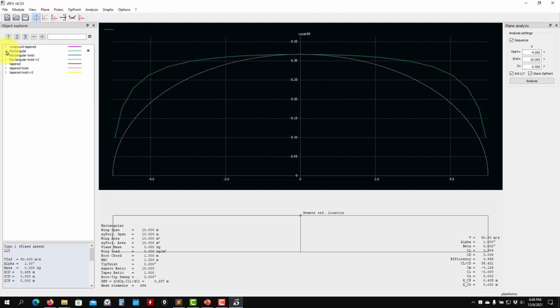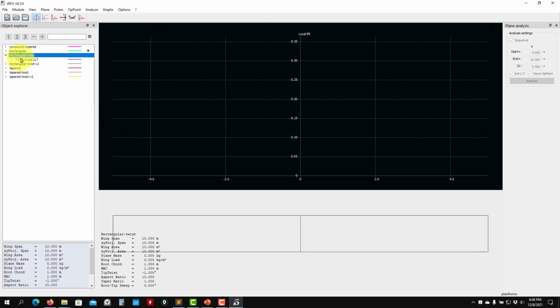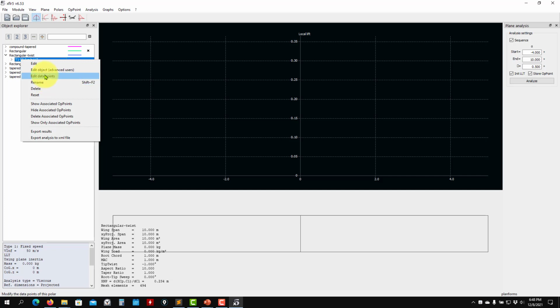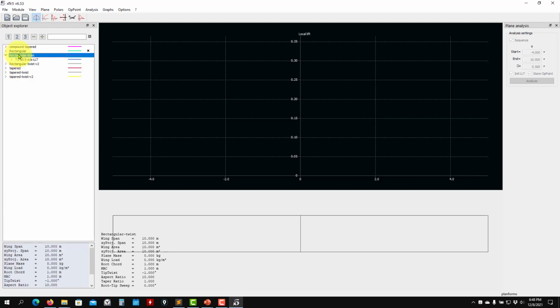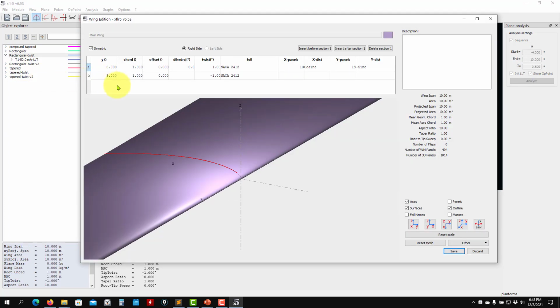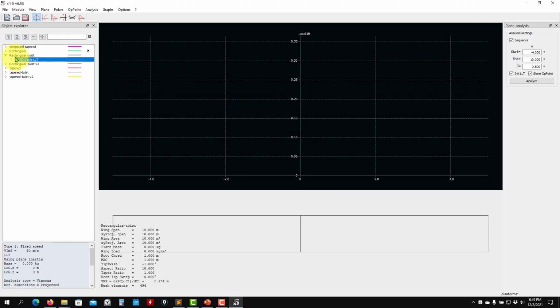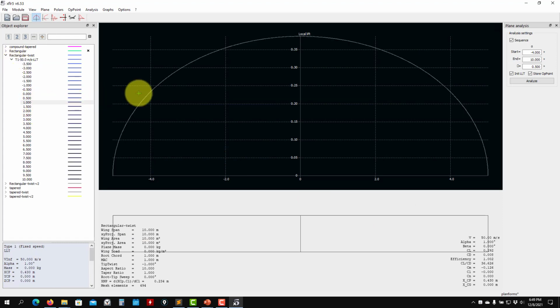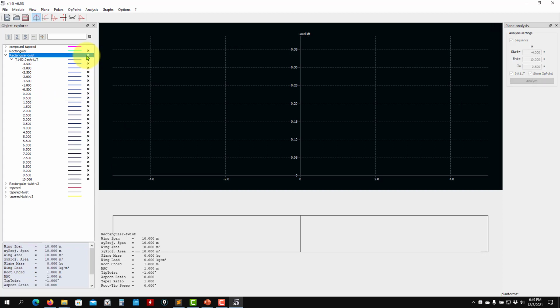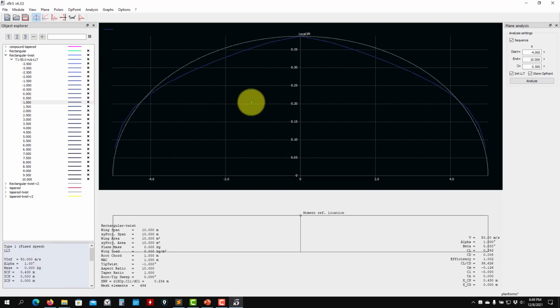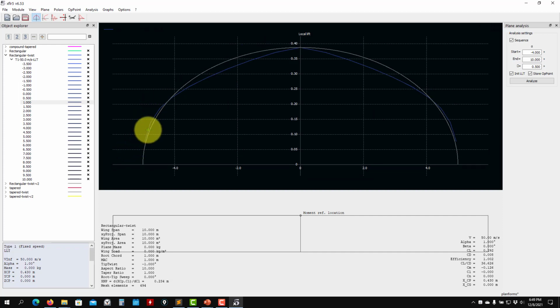So that is what we have in the second one that I have here, twist. I open here again and edit the wing. See that you have the values, and just add a twist from 1 to -1. And if we plot this one for 1 C, okay, enable here, and now I can see the value. See that now it is quite a good wing.